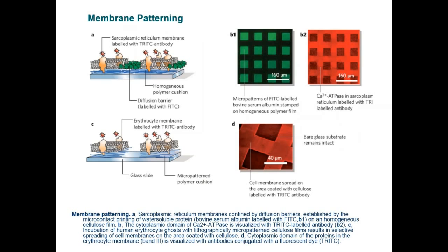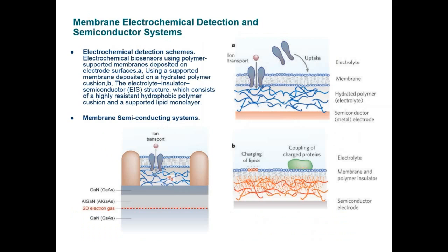However, membranes can also be integrated with a semiconductor device. The semiconductor device enables, for example, techniques like electrochemical impedance spectroscopy or other types of electrochemical methods, or measuring field effect transistors and eliciting the response of cells. In particular, neural cells, or even different types of barrier functions within the lipid bilayer, measured as a gradient on the conductivity, ion and electrical conductivity between the substrate and the membrane.